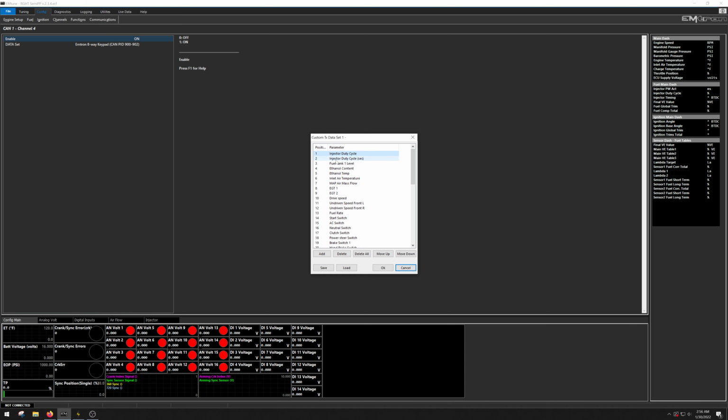So I've got primary injected duty cycle, secondary injected duty cycle, fuel tank level. This is most likely going to be an RX, right? Fuel tank level I most likely have on the PMU coming into the ECU. So not a transmission, but I'll get all this corrected and moved around as needed. Just taking notes now. But all these channels here will now show me to make a communication of the ECU to the PMU as direct and communicative as possible, so I can create parameters across these.